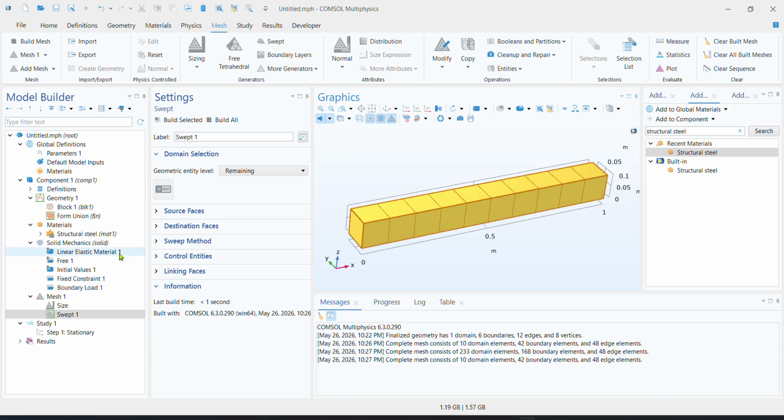It could be for linear elastic material properties, or for other studies whenever we try to emulate them. What it's essentially going to do in the end is integrate or consolidate all these different solutions at all these different nodes to give you one physical characteristic for this entire system. That is why we have mesh, which divides the solution space and helps the solver solve through and converge at a given solution.